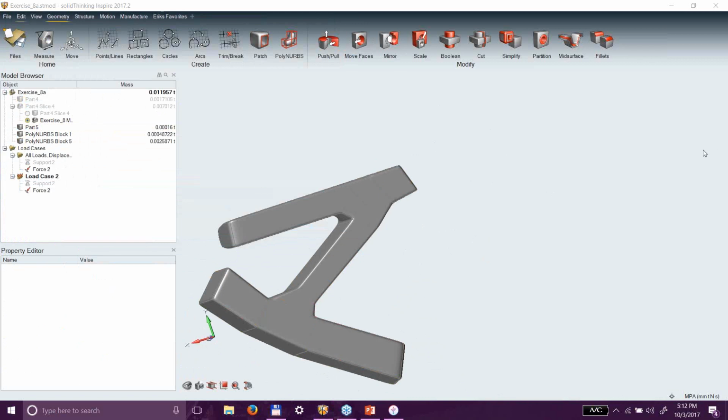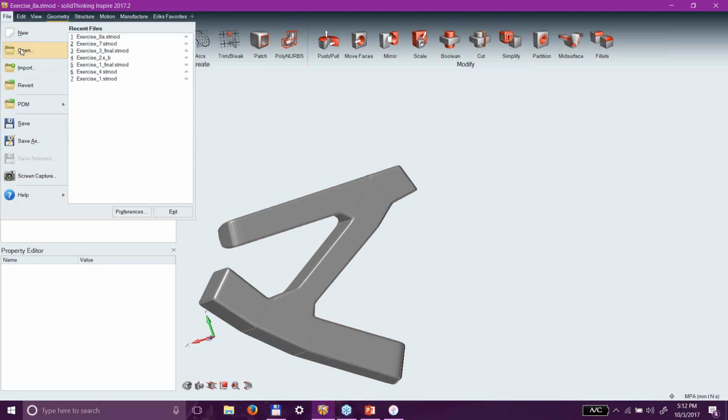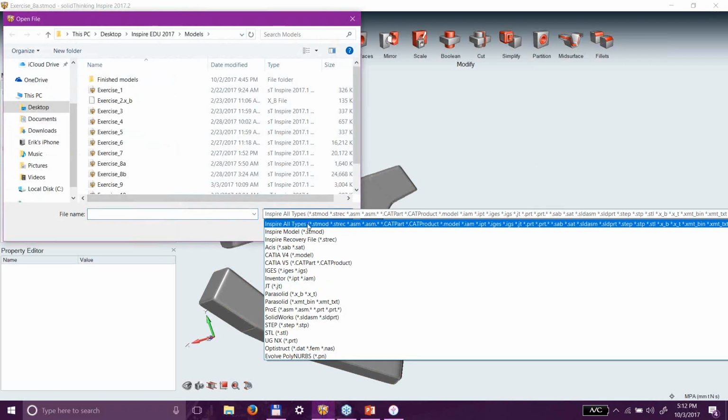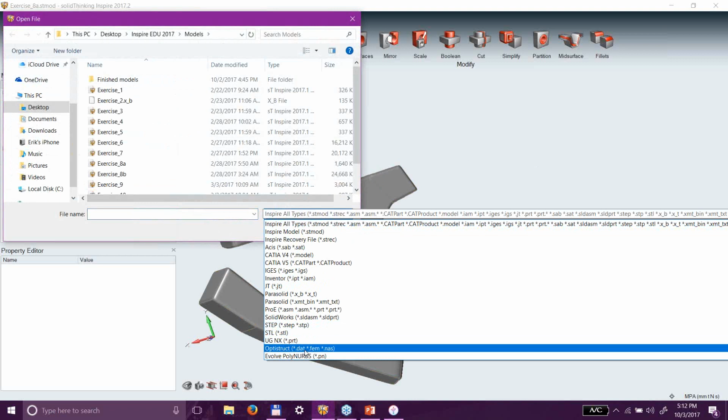Can you topo optimize if you exported an STL? Oh, no, wait a second. There it is. Is it possible to use those tools, PolyNurbs, with the standard optimization process, HyperMesh, OptiStruct? I guess yes, in that you could save your shape, and then we do have the ability to open, as you see here, an OptiStruct FEM file.